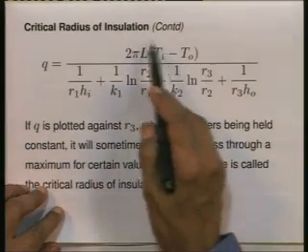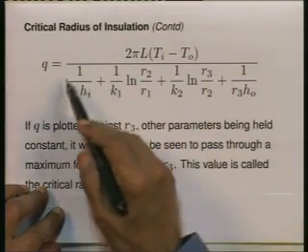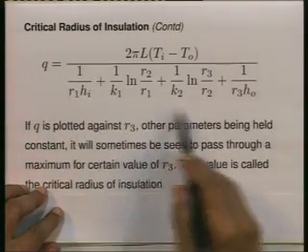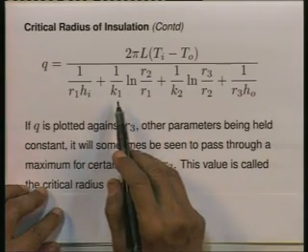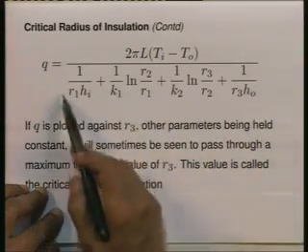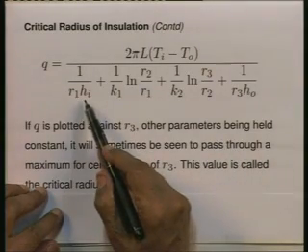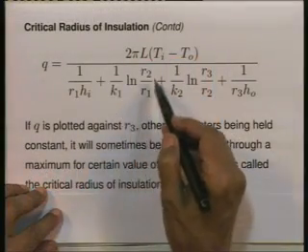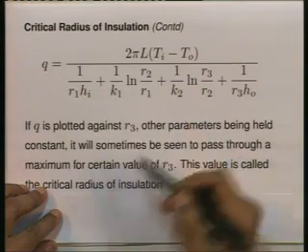We want to know where this expression goes through a maximum. The numerator here is a constant, all right. So, if I want to know where this goes through a maximum, effectively I want to know for what value of R3 the denominator goes through a minimum. So, let us differentiate the denominator only with respect to R3 and equate that to 0. The first term, if I differentiate, is going to give me nothing, because there is no R3 in it, it is all constants. The second term will also give me nothing, it also does not have an R3 which is our variable, it is going to give 0.